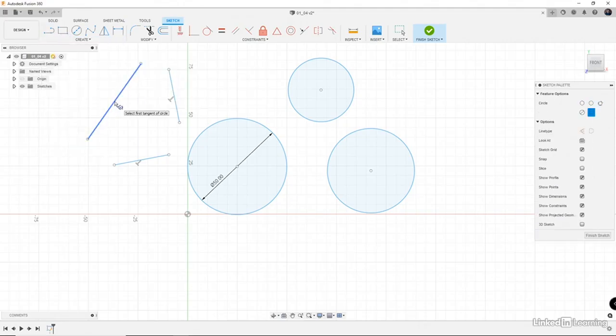So we specify a line segment, and then we can specify the diameter that we want. Now it will make sure that the circle is always tangent to those two lines. So kind of like I was talking about with how I use the 3-point, this you can use in a very similar manner, but adjust where along those two tangents you want it. Instead of specifying a point and then adjusting the radius, you always have it tangent, and you can specify where along those lines that curve is, that radius.